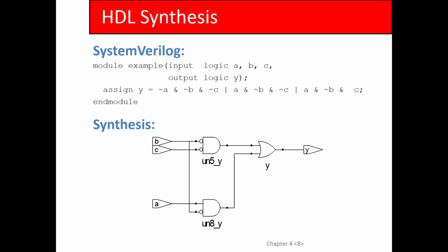But you'll get something that is minimal. Also, this may be subject to constraints. This is what might come out of the synthesizer, but when I map this onto real hardware, I might find that I don't want to do that because I may not have a 2 input gate that looks like this. So I may have to substitute something else, or maybe I want this to be deeper, more gate delays, but smaller gates.